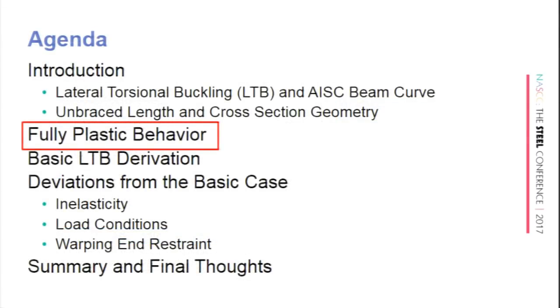All right, so with that, if we can have our individual plates with the appropriate slenderness, and we can have good effective bracing to get us into the plastic range, we can count on that fully plastic behavior. And that's where Perry will come up and talk to us about his depth of knowledge and research in this area.